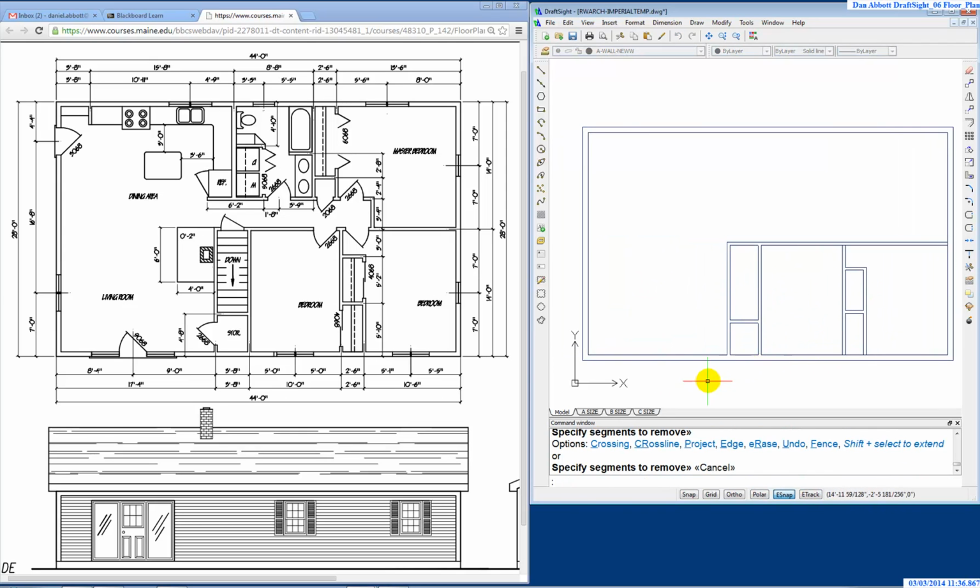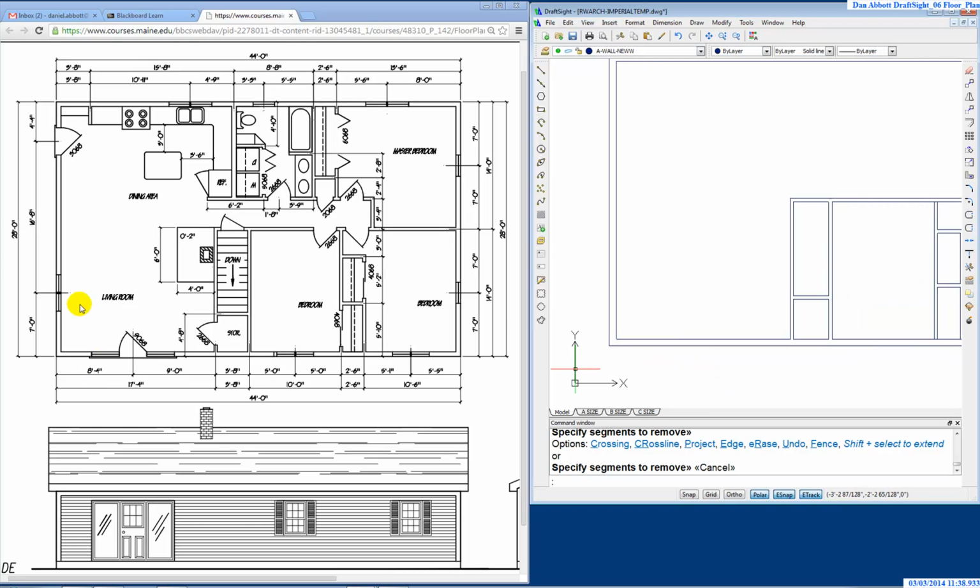So now let's put some openings in here. We'll go to the front door, which on the left hand side is right here. It says 90/68. That means it's 90 inches from here to here, and it's a 6'8" tall door. 6'8" is a standard door size. If you look at this little one, 26, it's 26 inches is the opening size. So that first number is the opening size in these cases.